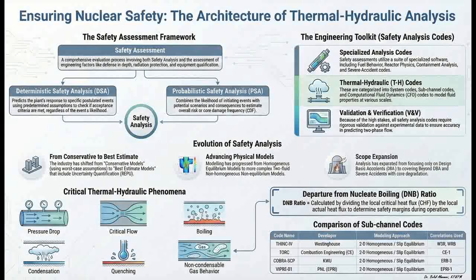Which is brilliant because it recognizes that nucleate boiling in a flowing system is actually two distinct mechanisms operating in tandem. It calculates the macroscopic convective heat transfer of the bulk fluid flowing past the rod. And superimposes that with the microscopic heat transfer of the bubbles forming and detaching at the wall. Giving you a highly accurate, continuous calculation of the heat leaving the fuel.